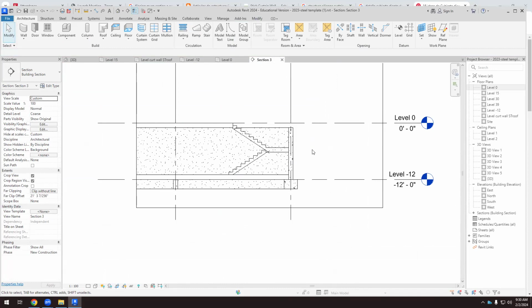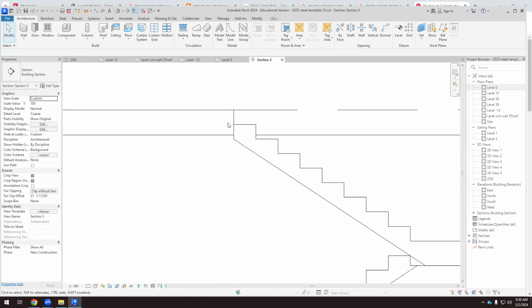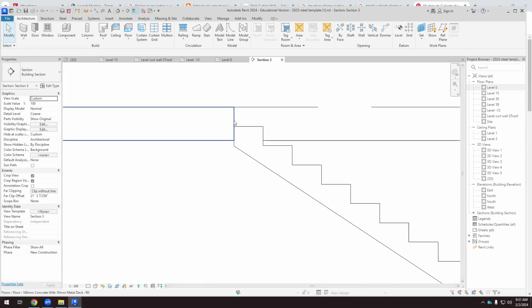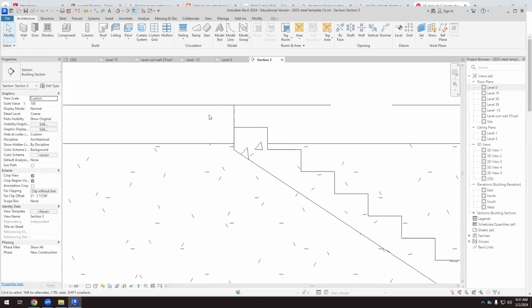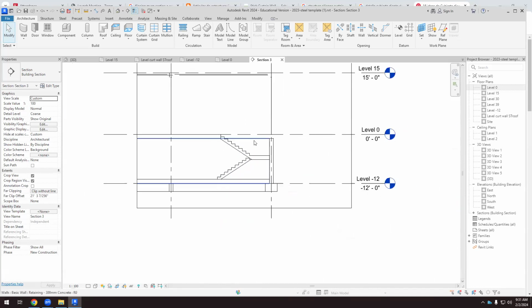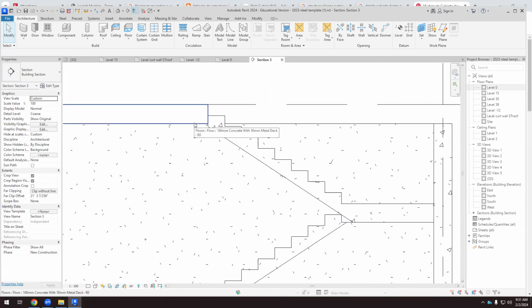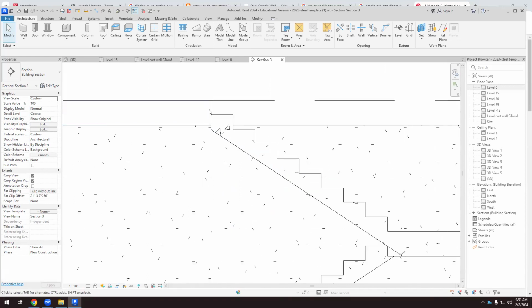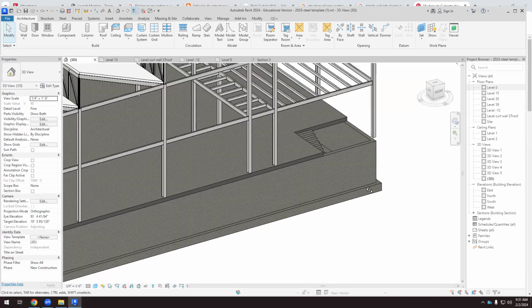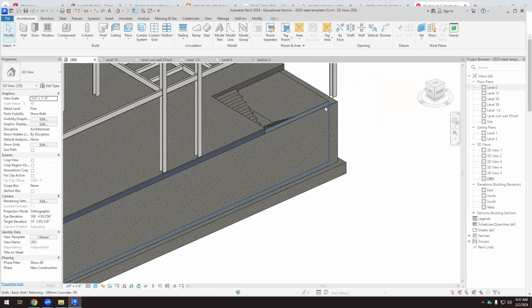In concrete elements, well, we will need a reinforcement here. Every time we open something, we need the structure to frame it. Okay, so in the concrete structure, we do that by reinforcing this part of the slab. So there will be more reinforcement at this point, but it doesn't affect the architecture. So okay, it will affect the reinforcement that I have to design here in this part of the slab, but that will work. And now I see, oh, I did something wrong.